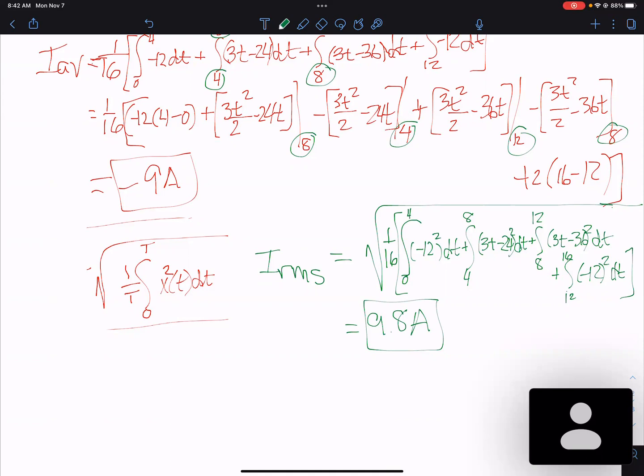But yes, we can use these values to actually find that complex portion of it. But these do effectively give us what the DC value would be if we were to measure these. So when you measure on an oscilloscope, you'll see the full waveform like this. But if you use your digital multimeter, you're going to measure an RMS value. So hopefully now you understand what that RMS value is and where it comes from.